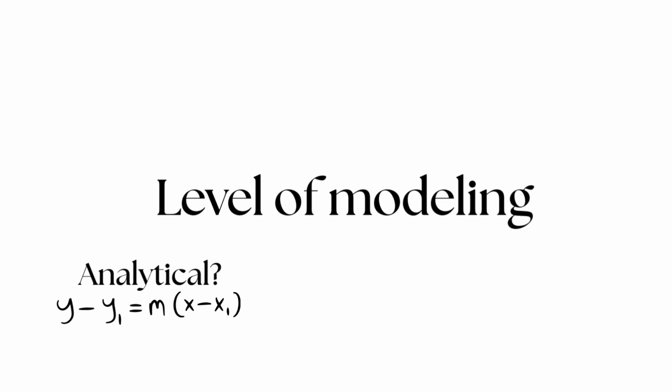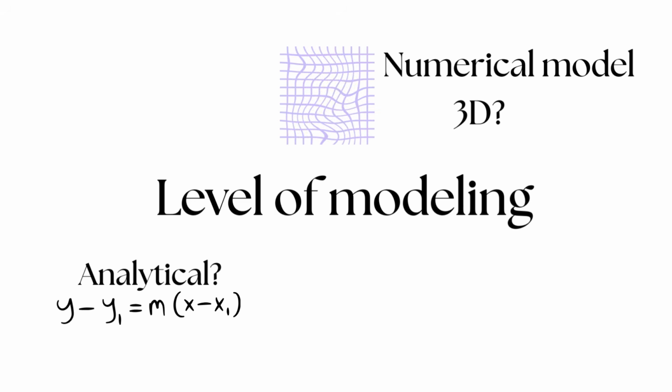So the first step in simulation is not choosing the software, it is choosing the level of modeling. Can I reduce it analytically? Or do I need a numerical approximation? And if I approximate it numerically, do I need it to be 2D or 3D, and etc.? That decision alone separates engineering thinking from just button clicking. So let's move on to the numerical methods available.